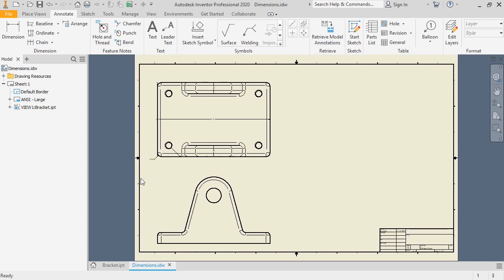To move the dimensions, you can either click on the dimension text to move it, or the green dots that serve as drag handles. As I rearrange the dimensions in the view, you can see that some dimensions, like the dimension for the extruded hole, would actually be clearer if they were shown in other views instead of this one.